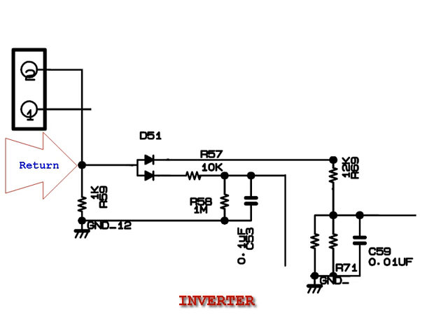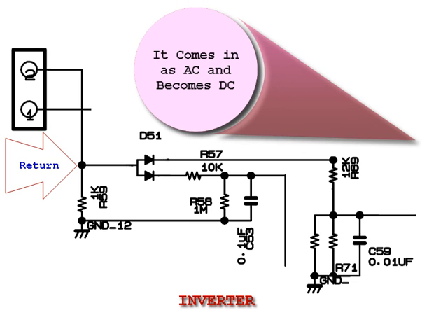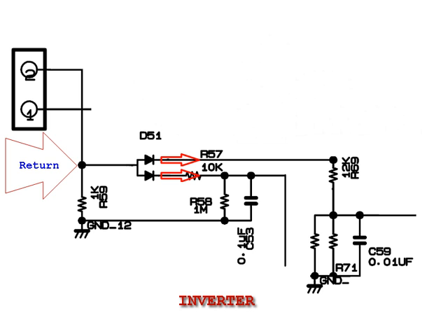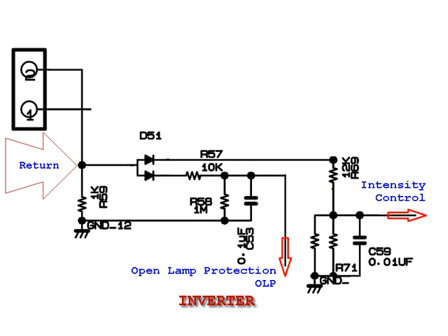The first thing is to make such sample pass by a rectifier circuit to convert it into DC. This is possible through two different circuits, one for intensity controls and the other to detect if any lamp becomes open or disconnected.